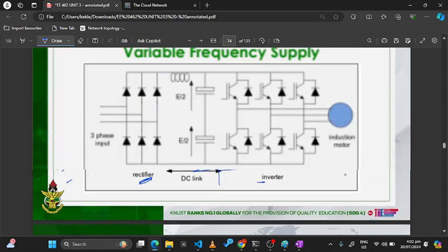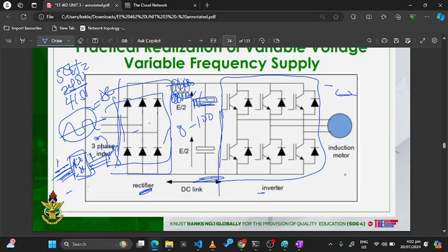Actually, shoot through. You've done power electronics, so you know shoot through. During changeover, sometimes a device that is supposed to go off before another one comes on is not totally, completely off, and the one that's coming on has already come on.